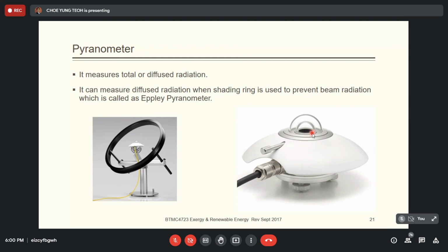And then next one, I haven't talked about the function of this. This one we call the sun shield. Actually, it's to protect against reflection from the ground. You can see that the sunlight from above will hit the ground and reflect to the sensor. But if I have the plate over here, whatever reflects from the ground will hit the bottom part of the plate, so it will not reach the sensor. So this is the main function of this sun shield. But of course, they have designed this shape and this color.